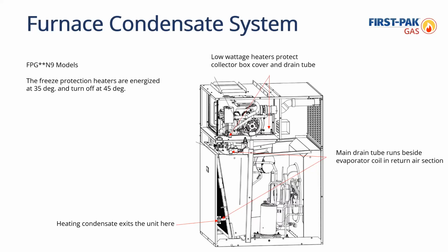There's other manufacturers where they will run the tube on the exterior, and then you have to have heat tape or some sort of freeze protection on that tubing. We designed it so that it runs inside the cabinet as much as possible to further prevent that freeze-up, and then also as a cost reduction, kind of one less thing that the contractor has to do during the installation.